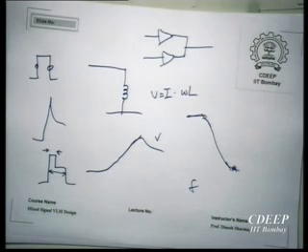If you don't want that, then what you should do is to have a buffer and send the data very, very fast and then turn off this thing so that you don't waste static power. But if you send data at low speeds, then we have a disadvantage because we always draw this much current and therefore we consume static power. So we don't look so shiny when the data transmission is at low speed. Over a long period we will consume huge amounts of power. So we need to turn these things off, and that is one big problem for this.